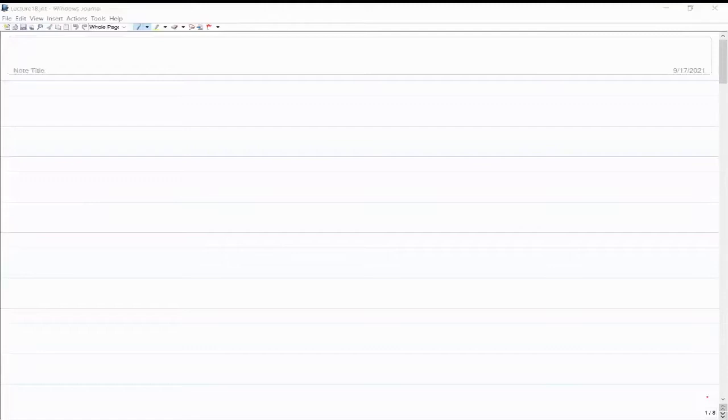Sir, I am still not clear. In isotropic hardening, we are taking F as a function of sigma and the plastic work WP, the plastic work of stresses. And alpha, the back stress, we are not considering in isotropic. And in kinematic we are considering just sigma and alpha.